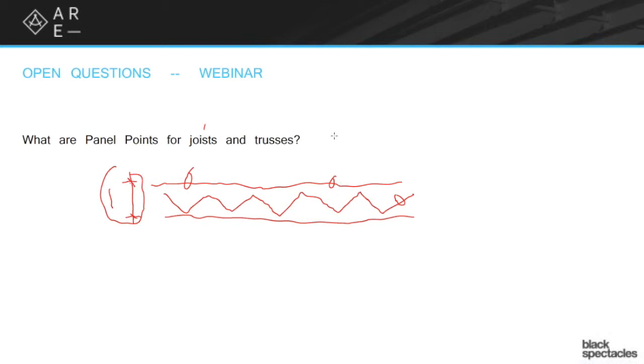Well, if I started to put a giant load directly onto that 2x4, that 2x4 is going to start having its own set of problems, right? It's not going to be that the overall truss is now loaded. The question will be, can that 2x4 hold that particular load? Let's say it was a giant air conditioning unit or something like that. So what I want to do, if I can, is instead of putting a load randomly located on the truss, I want to put a load right where some of these pieces are.